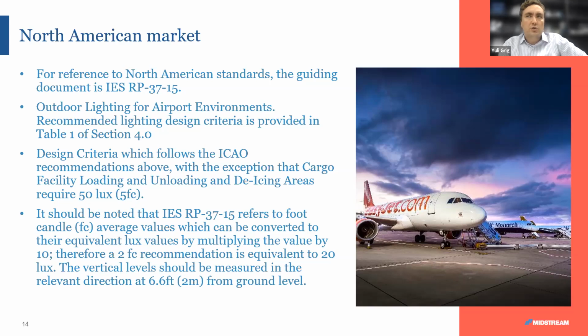I think we should remember that the US system uses foot candles as opposed to lux levels, but they're pretty similar. So as a rule of thumb, 2 foot candles means 20 lux. So you basically multiply the foot candle by 10 to get to lux.